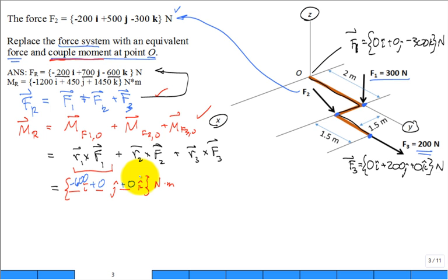When you get a really complex force and a really complex displacement R, then yeah, you should rely on doing the cross product mathematically. But this one you can do using your right hand, can't you? So if I look at it, this force is only in the z direction, true? It's downward. And it actually goes right through the y-axis. If it goes right through the y-axis, can it induce a moment around the y-axis? Make the object want to rotate around the y-axis? Cannot. And so right away I can tell that this part is 0.